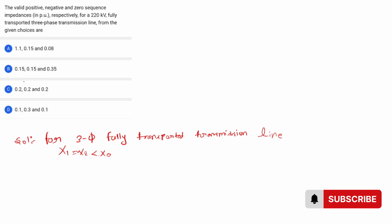Option B has X1 equal to X2 equal to 0.15 and X0 equal to 0.35. So positive sequence impedance equal to negative sequence impedance is less than zero sequence impedance. These criteria match option B, so option B is the correct answer to this question.